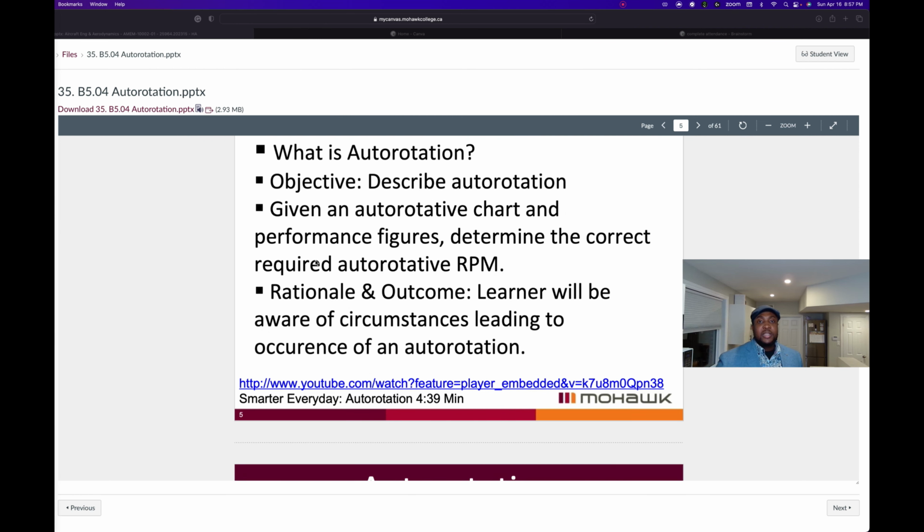The altitude speed chart, also called the height velocity chart, illustrates the helicopter's auto-rotation capabilities, and this is different for every aircraft with regards to the helicopter's height above ground and its speed. The shaded areas are places where you should avoid operation for continuous periods of time. The one on the left is known as the dead man's curve, or the coffin corner.